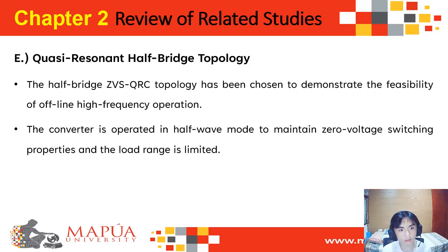Next, quasi-resonant half-bridge topology. The half-bridge ZVS QRC topology has been chosen to demonstrate the feasibility of offline high-frequency operation. The converter is operated in half-wave mode to maintain zero voltage switching properties, and the load range is limited.